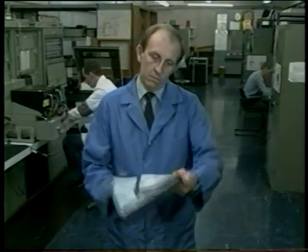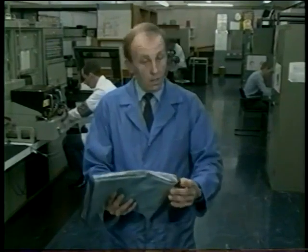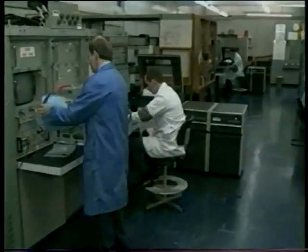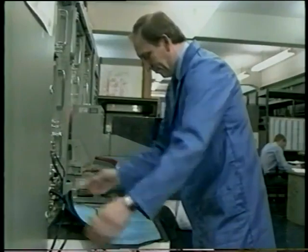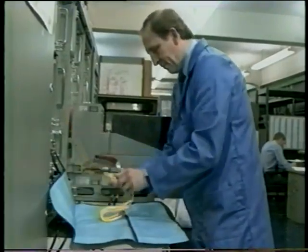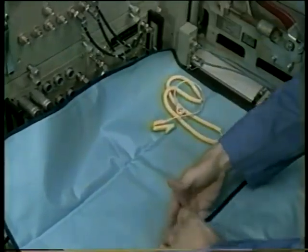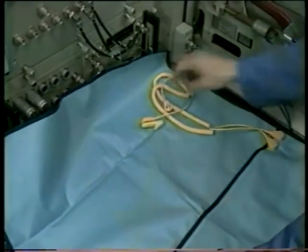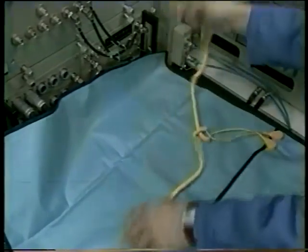That's all very well while I'm in the bay, but what happens when I'm on detachment? I can't take my bench with me, can I? This is where the field service kit comes in. The field service kit is a portable special handling area which provides a dissipative work surface with wrist strap and ground cords. It can be used as temporary protective packing for ease of transportation. It allows freedom of movement and is not restrictive in any way.